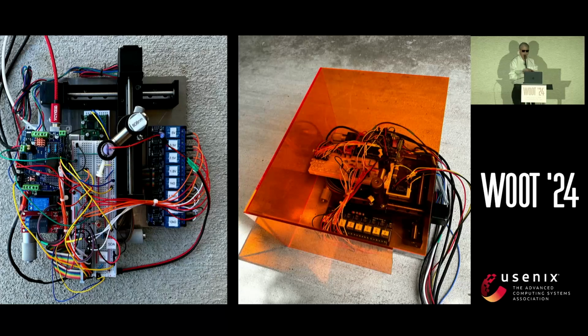So we built this infernal machine. It consists of a pair of linear actuators, the x-axis one bolted on top of the y-axis one crosswise, so we can raster scan a focused laser across any desired component on the circuit board, stopping every 50th of a millimeter to measure the voltage on the communication bus. There's a live I²C bus under there, and it's communicating the whole time.